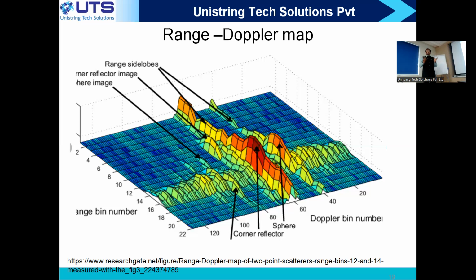And if you do some digital beam forming with multi-antenna arrays, you will be able to tell more precisely within that 6-degree sector. So the direction is not there in the RD map. It is there at the time at which this RD map is created. You understand? My servo is rotating, the radar is rotating, the beam is here. Now I get an RD map where I have a range of 1 kilometer, velocity of 10 meters per second. Because my antenna is looking at some 30 degrees, I will tell that in the 30 degrees direction, I have a target with velocity of 10 meters per second and range of 1 kilometer. You got it?